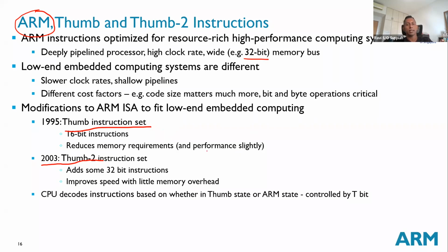Okay, so again, this is just the history of what happened and why you have these 3 variations: ARM, thumb, and thumb2. Again, this only matters mostly if you are dealing with low-level assembly language coding. Since we are writing in C, we don't really have to worry about this so much.